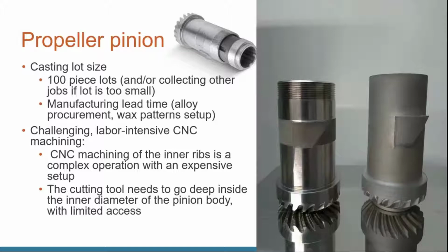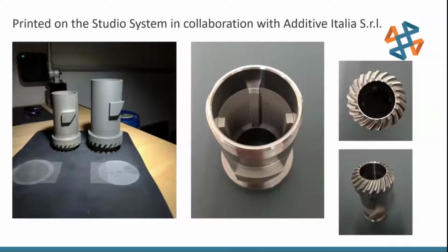So on the right of that picture, we have the part straight out of being sintered, and then on the left is when they did the post-machining operation. Not over the entire part, just in the areas that it needed it for critical surfaces. And then you have a finished part, and you put your threads in because it's a full strength end-use metal part. You can see some more views from there, the inside deep wells that would be very tricky to try and CNC machine all the way down there.